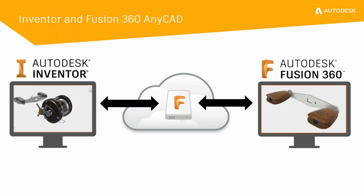Likewise, the new AnyCAD workflow allows you to take advantage of the power of Inventor and Fusion 360 together. Here you can bring Fusion 360 models directly into Inventor for things like system integration, or maybe it's large assembly design or documentation. The good thing is that when the Fusion 360 design is updated, the change will automatically flow through to Inventor. And likewise, if you're referencing an Inventor model inside of Fusion 360 for things like maybe cloud-enabled simulation or CAM, because Fusion 360 now uses the same AnyCAD technology, changes in the Inventor model can be automatically consumed in Fusion 360.